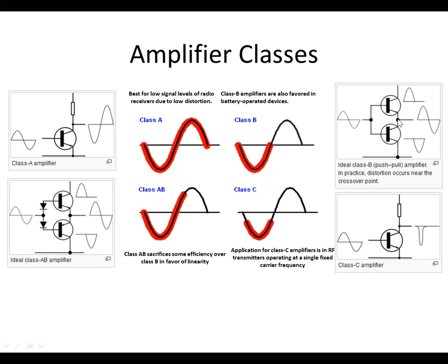So you can see where it's a little non-linear when you get down to 0 volts, because there's the forward bias voltage of a transistor. If it's a silicon transistor, it's about 0.7 volts. Germanium's about 0.3. So there's a little discontinuity when it goes through the minus 0.7 to plus 0.7, and causes a little distortion on a Class B amplifier.